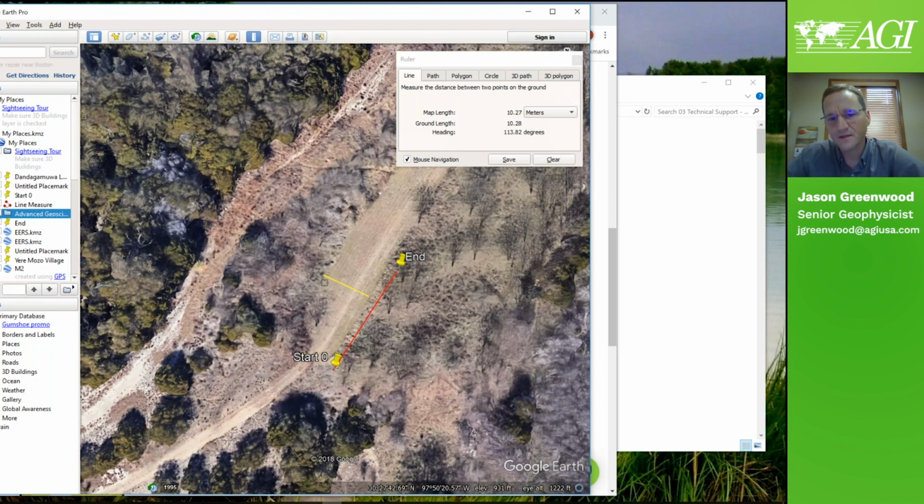They may know from a neighboring building what the depth to bedrock is, and they're not sure here. And of course, if it's twice as deep, that's twice as much excavation and earth removal, and changes costing for the engineers. So the idea is you reduce the amount of drilling to ground truth and cover a much larger area. Maybe just do 1 or 2 spot drills in there.